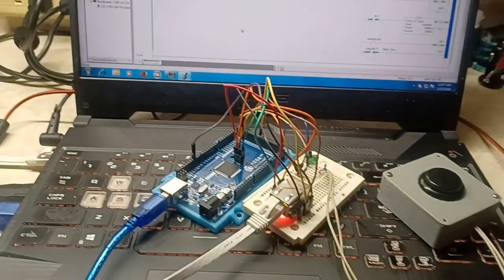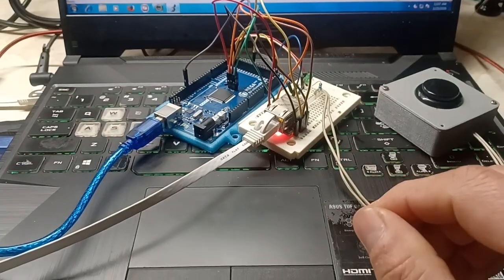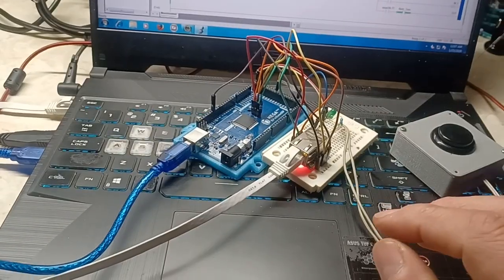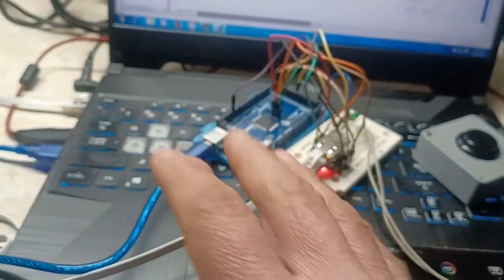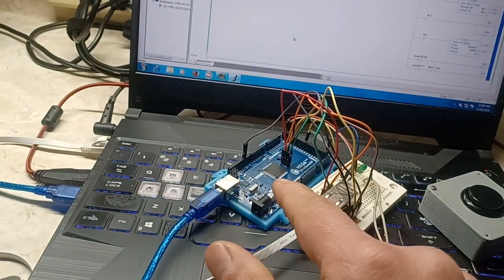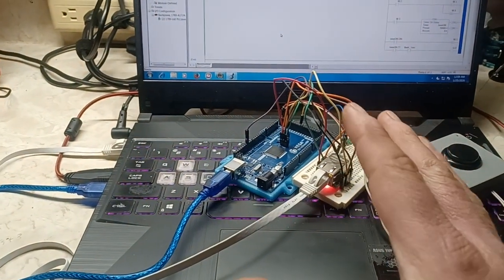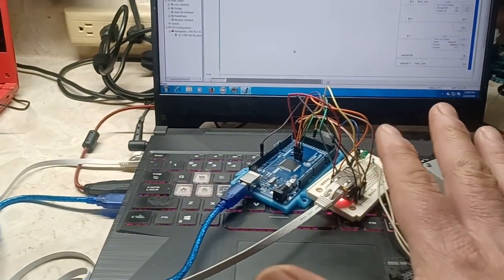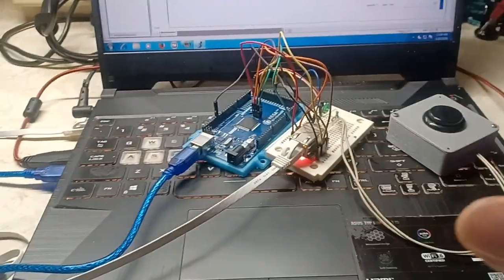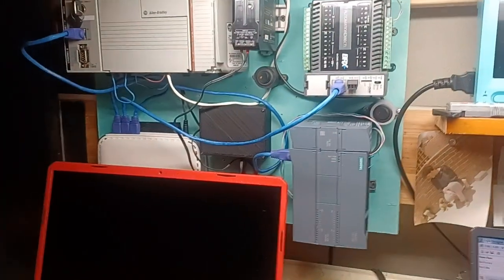So this is the soft PLC, Softlogix, kind of communicating through OPC-DA with Kepware. And then Kepware bridges communications between OPC-DA to Modbus TCP, and then reads and writes from the Arduino Modbus TCP. This, of course, is not recommended for an industrial setting, but this could allow you to test logic. If you're going to test some exotic code and you don't have a real PLC, you don't need to have the whole thing like I do over there.